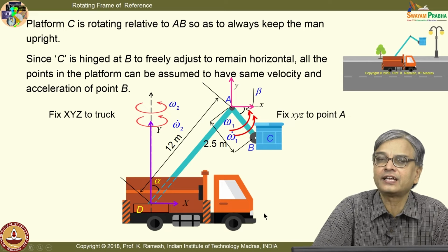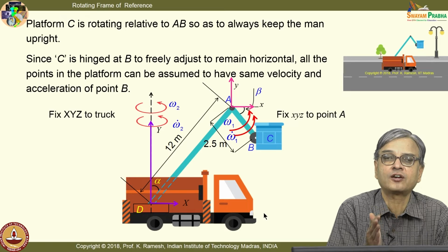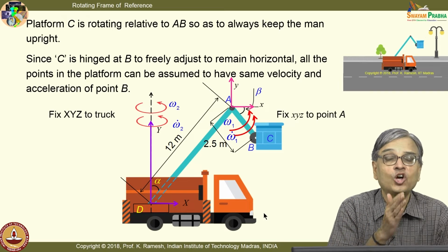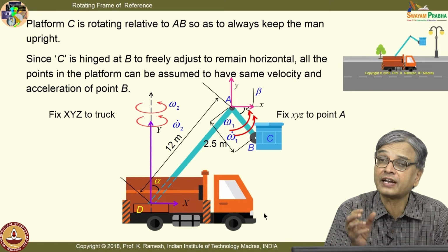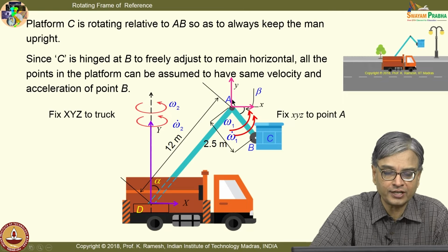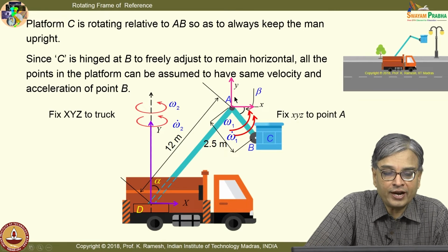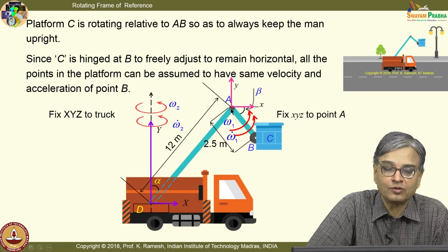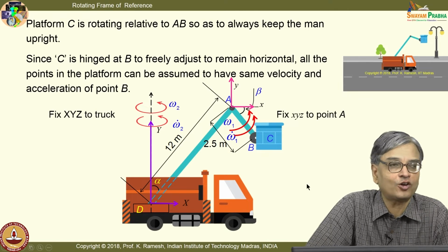So, I have no difficulty in handling the expression, because when I say VA equal to VB plus omega cross R plus VREL, they are all referred to different coordinate systems in a generic problem. So, you have to use the vectors properly, fine, and here no such confusion is there, but the only confusion is that what we used as point A has become point B, and what we used as point B has become point A. So, you have to know how to write this expression, and the motion is easy to visualize, there is no difficulty at all.